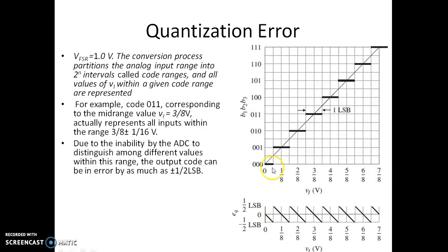Now you take that same 1 by 16 or slightly more than that. Just consider a voltage which is here. Now that input voltage will be represented by 011. So actually this is not exactly equal to 011, but you are still representing it by 011. 011 actually corresponds to 1 by 8.